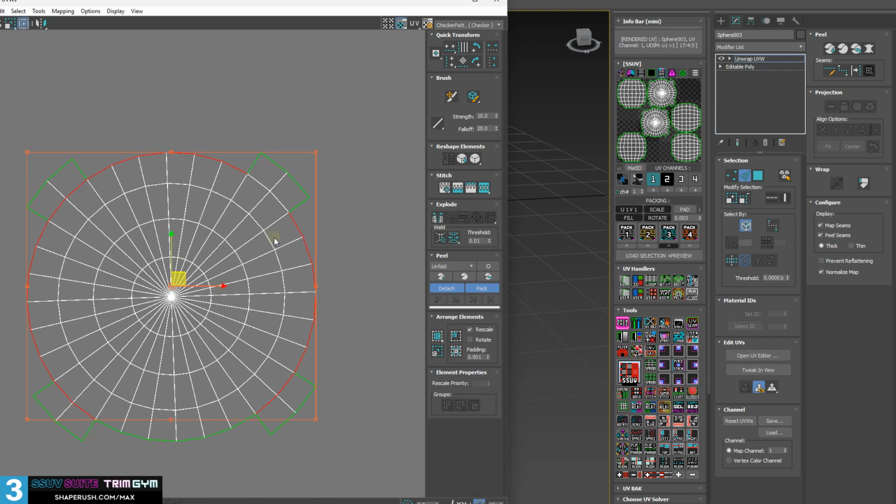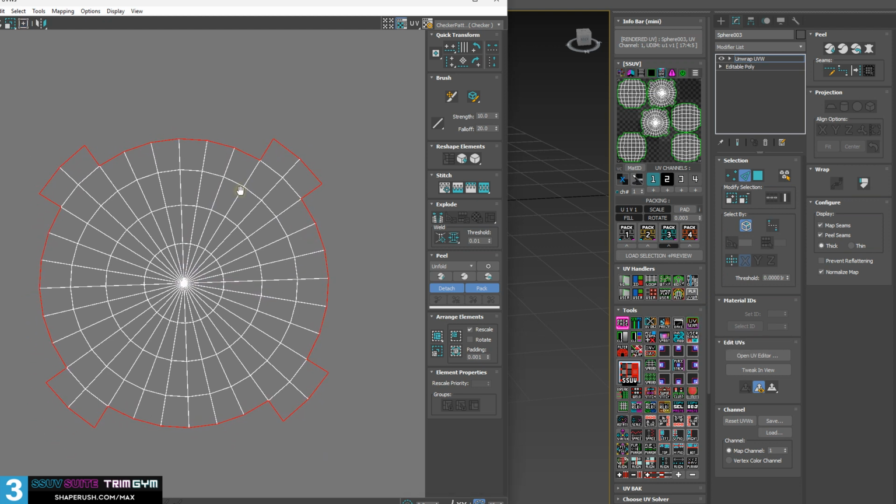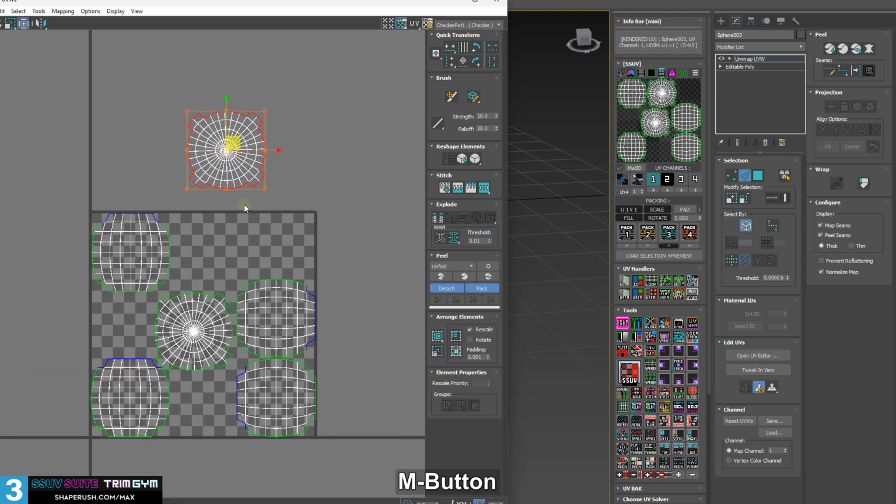I would like to select that seam. So what I can do is select one seam on that element, then left-click. They'll automatically select the seams for me. If I would like to select all of the seams for my entire selection set, I would select no seams at all. And yes, you have to be in edge mode for this. I should have mentioned that. My apology. So be in edge mode, have no seams selected, then click UV Seam.